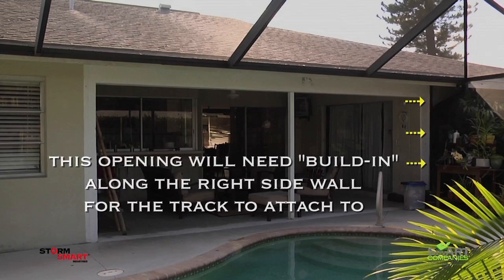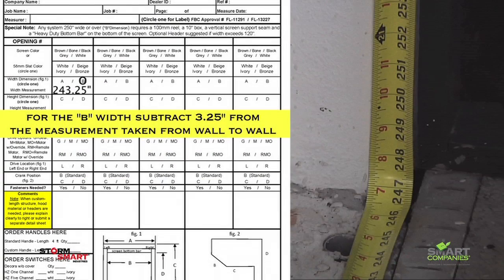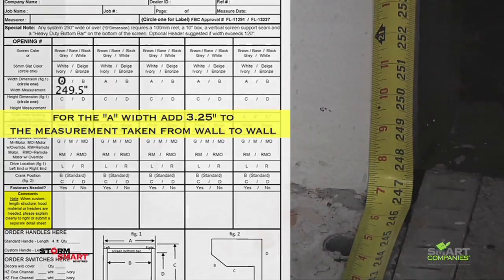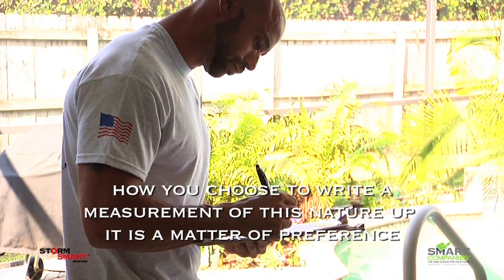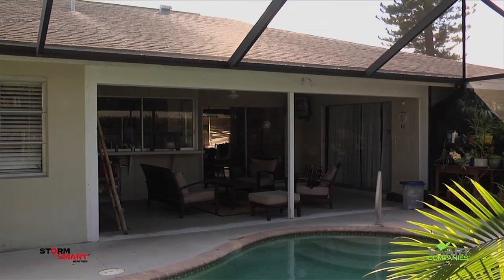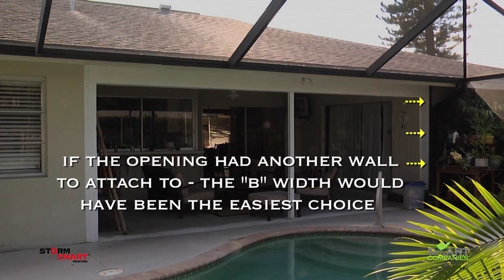To come to our B width measurement, we'll subtract 3¼ inches, the width of the rolling screen track, from the measurement we took. To come to our A, or overall width measurement, we'll add 3¼ inches. There is no wrong way to write the measurement up, it is a matter of preference. If there had been another wall to attach to, we may have simply used the B width measurement.